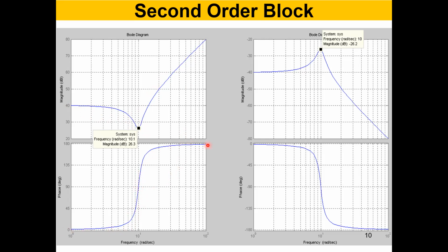Eventually, the total phase is 180 degrees. A 180-degree phase change means one half of the cycle. So therefore, when you have the input going up, you can see the response going down. The response starts the second half of the waveform, right? So an exact upside down waveform, right? But this happens when the frequency is very, very large, like 100 radians per second, okay?